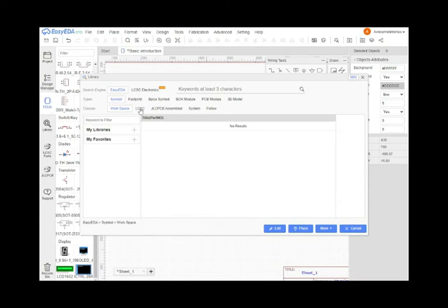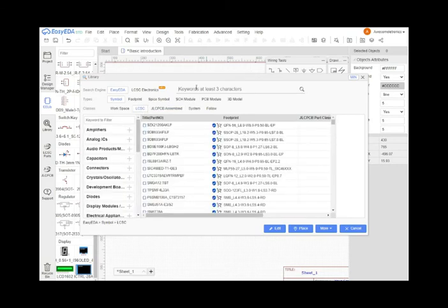I recommend you search first in system or the PCB assembled or the LCSC, and there will be one segment called user contributor, and it's fine using them too, but sometimes they don't have footprints. Footprints means the designated holes for the component placing after, for the soldering.